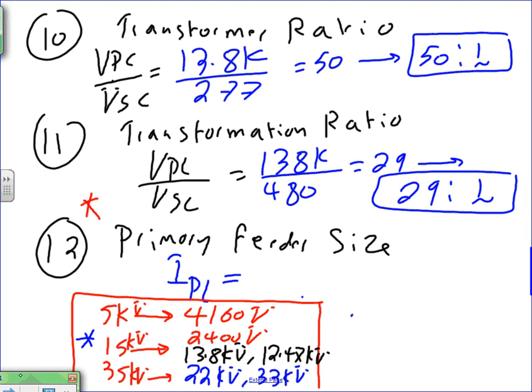So when I size the primary, I have to go to the line current, like we've done in the past, and I have 9.4 amps. Now I bet William is saying, Chad, I can carry this with number 14. Hold your horses. Had this load been 600 volts or less, number 14 would be good enough, right? But remember, the voltage that this cable is carrying is 13.8 kilovolts, so your cable has to be a 15 kV feeder.